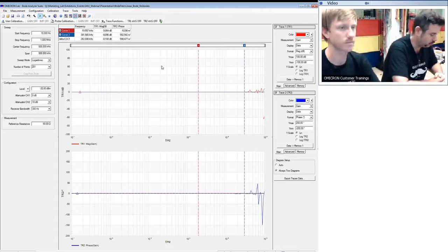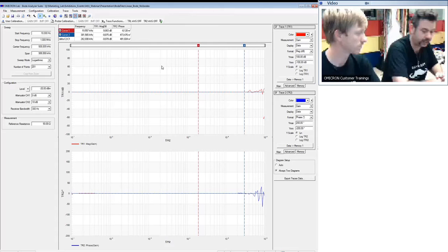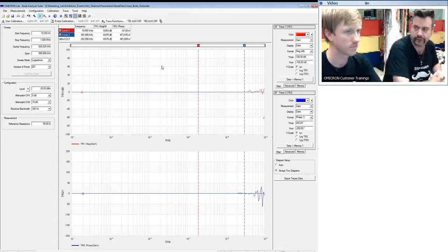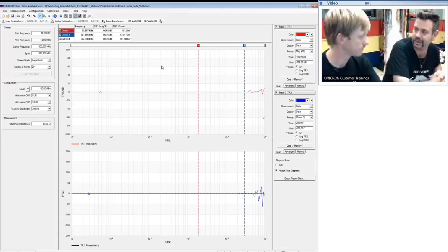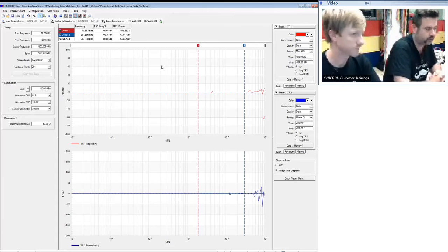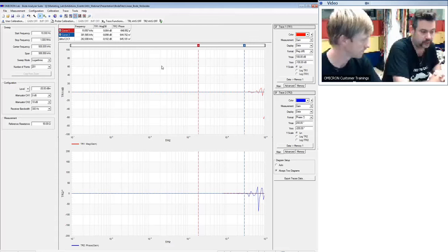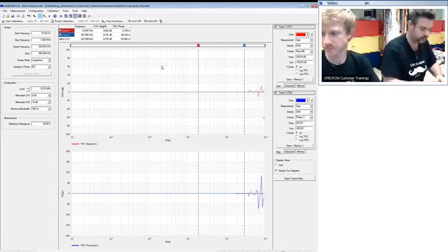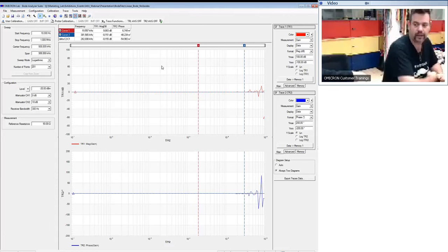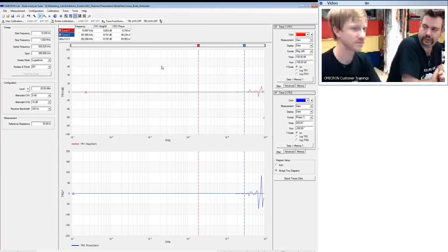Further on, also this test is very important to find out if there is, for example, a problem with injecting signals into the braids, into the cables of the probes. I once had a case where we measured a LED driver with very high currents, and it was, as usual in the lab, a kind of messy environment with a lot of cables, and we had the problem that one high current cable was in parallel of one of the probe's cables, and then depending on how we moved the probe, the phase changed. And so we were not able to measure the phase margin. So it's always good if you make this test and then you move around your probes, then if you still have a flat line, you know that everything's working. Okay.